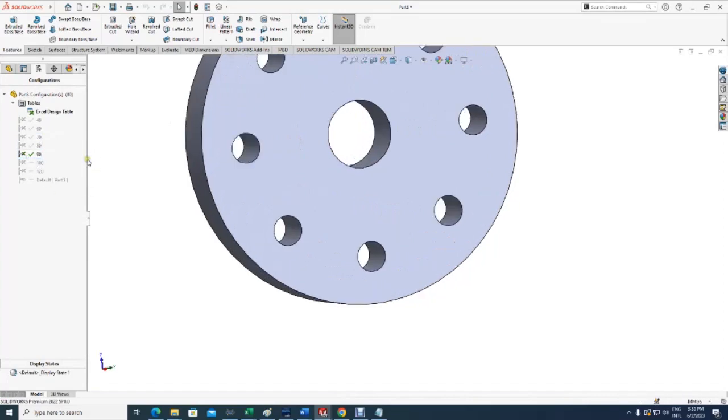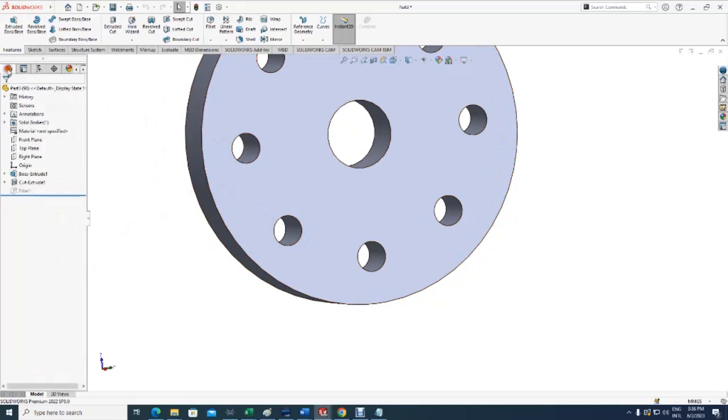Well, the problem is that SolidWorks thinks that what you designed only belongs to the 40 part and not to the others, although everything is within the package. You got to go back here for a second and check what's happening with the flat.